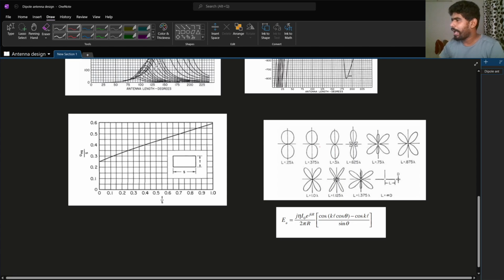So the antenna is actually placed like this, and this is maybe only for your understanding. This will be the coaxial cable, connected here. This will be the lambda by 4. In that case the radiation pattern will look like this. What does it mean? There is no radiation on this side. Theoretically it's zero, but practically we can see some radiation, and this will be the maximum radiation area. When you increase this length a little bit, it maybe becomes like this area.